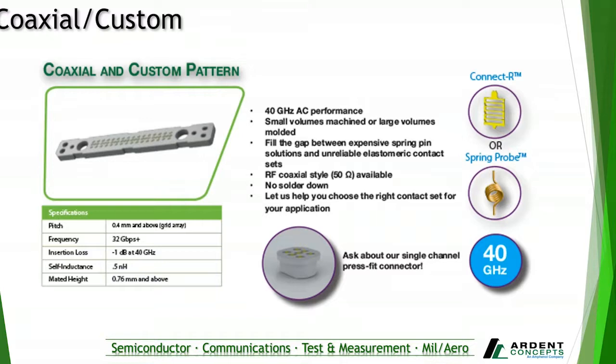Another type of connector system we offer and that our customer base has been quick to adopt is our coaxial pattern interposers. It utilizes the same coaxial structure that we use in our TR multi-coax product, and customers with RF signaling needs at very high signal integrity can get a connector system in a 4, 8, 12, 16, and 24 channel configuration. The signal-to-signal spacing in our standard configuration is 2.54 millimeters, providing for a crosstalk near or at our instrument floor.